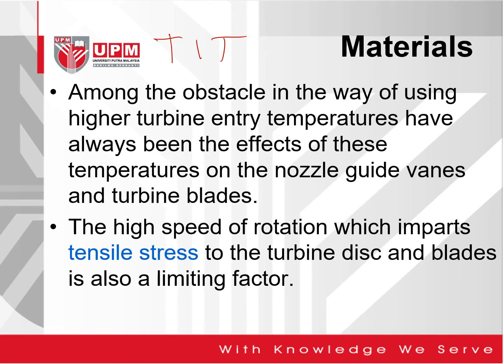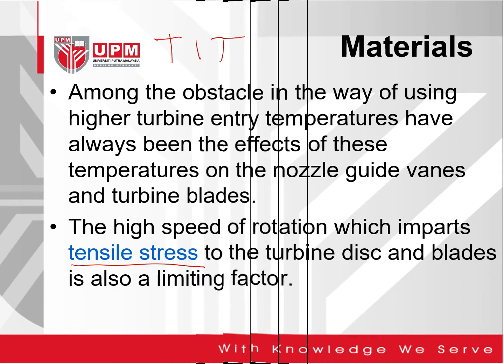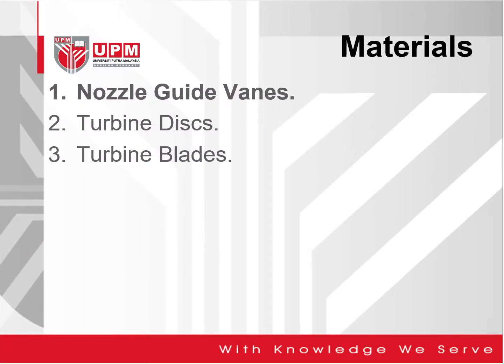The high speed of rotation, which imparts tensile stress to the turbine discs and blades, is also a limiting factor of the turbine. We shall look in more detail at the materials for nozzle guide vanes, and we will continue on turbine discs as well as the turbine blades.